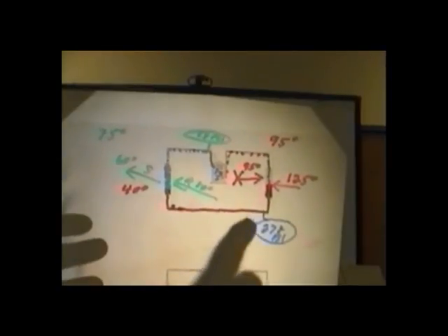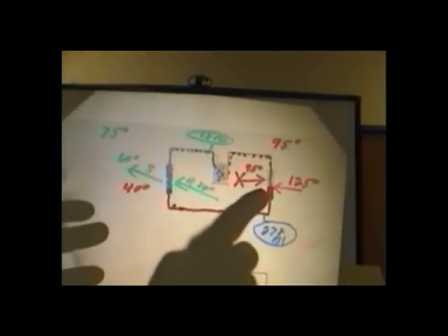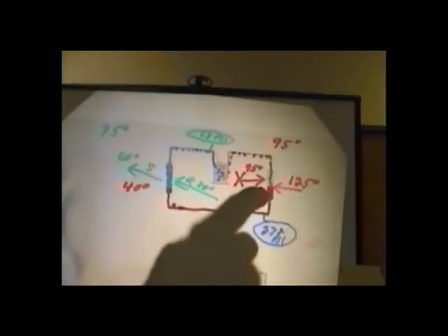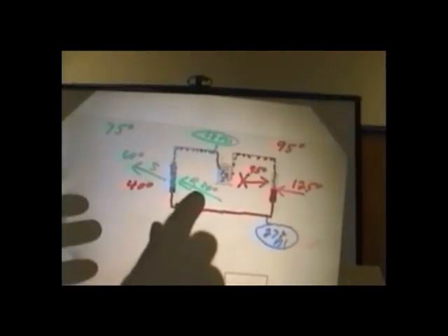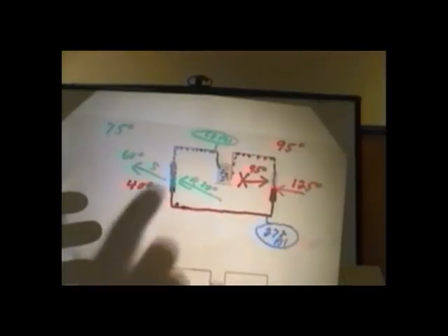We put the pressure gauge on the high side to know what the change of state temperature is, although we know it's vapor on top and liquid at the bottom. And we put our pressure gauge on the low side to know what our evaporator temperature is, and the whole thing is full of liquid, boiling, changing state, picking up BTUs from the return air, and of course the supply then comes out cooler. And all that's left now is vapor. Okay? So now we know how to get the temperatures.